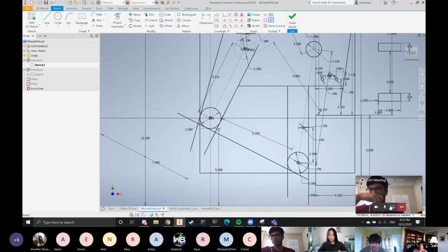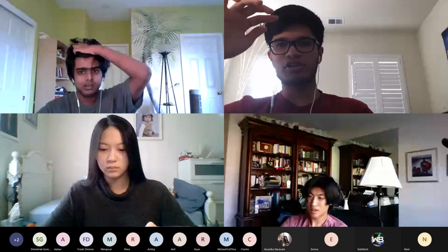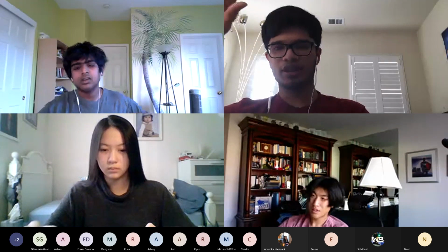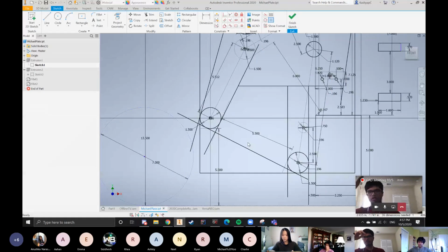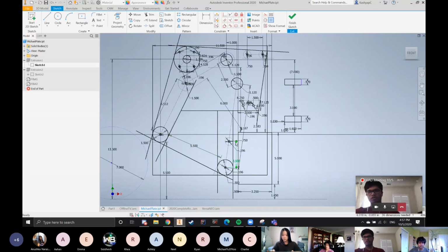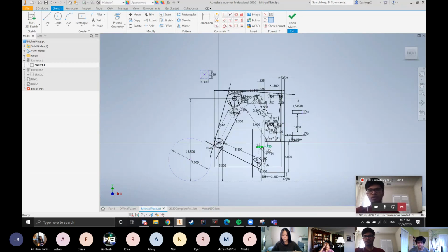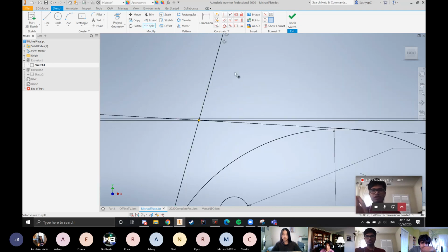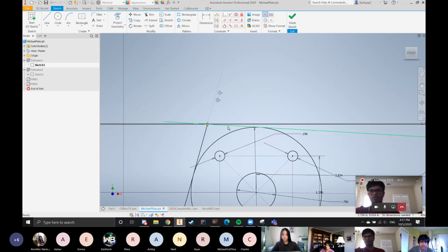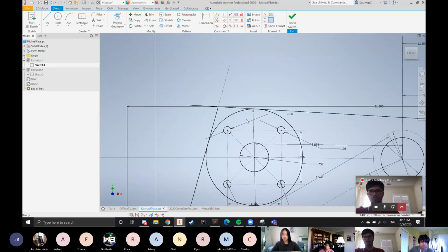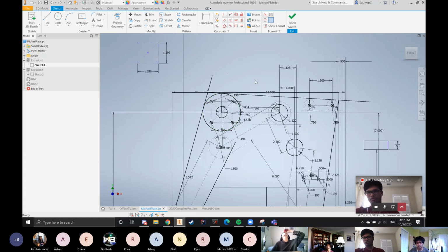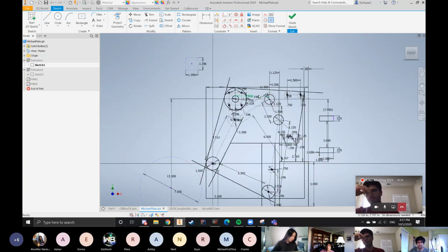Yeah. And sorry, if I could add something, if you wanted to go back to the sketch too, that would be cool, because it just shows better. When you're making a sketch, like what Kashyap said, you can add all these extra lines. What helps, I found, when you're trying to extrude it, is there's a tool up top called split, and you can split different lines and then turn different lines into construction lines. When you turn that into a construction line, it doesn't give you the option to extrude it, but it keeps it in the sketch so you can see them visually. So in Kashyap's example, I would probably do that with the centering wheels and with the bumper and those kinds of things, so that you don't have any problems there.